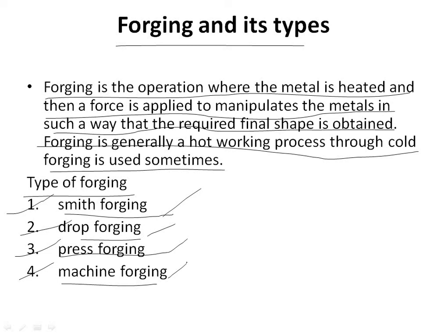As it involves the upsetting operation, sometimes it is known as upset forging. Originally, this was developed for making bolt heads in a continuous fashion, but now there are a fairly large number of diverse uses of this process because of the beneficial grain flow obtained from upsetting. It is used for making gear blanks, shafts, axles, and similar parts.